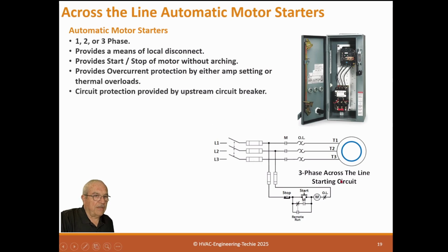And here's that standard circuit you see. So this is the disconnect device. Then we have the contactor in here, which has motor overloads, which might be thermal heaters or might be actual amp overcurrent. It has the contactor. And then we have start-stop buttons. Start and stop button. And then we also have this coil here, which is basically remote start. You close this and it actually does remote start. Closing this coil, closing this contactor.